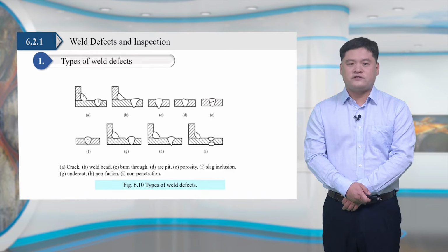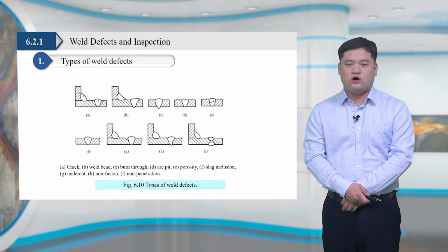There are many reasons for cracks, such as improper mechanical composition of steel, unreasonable selection of welding process conditions, such as current, voltage, welding speed, welding sequence, etc., and the surface oil stain of welding parts is not cleaned.